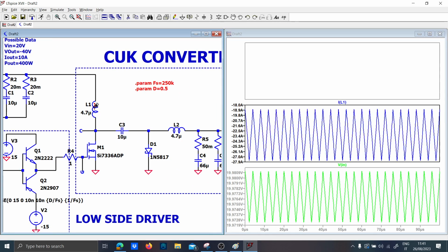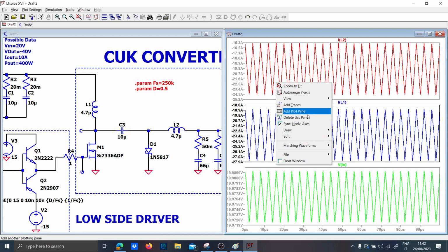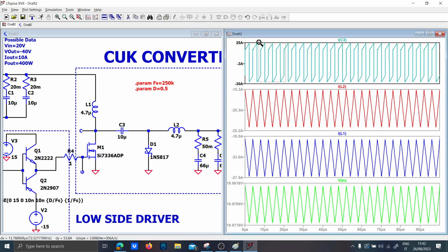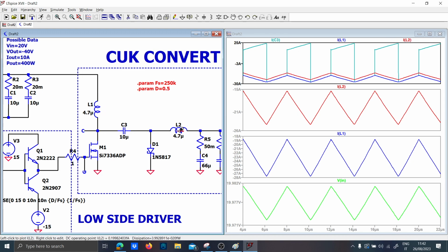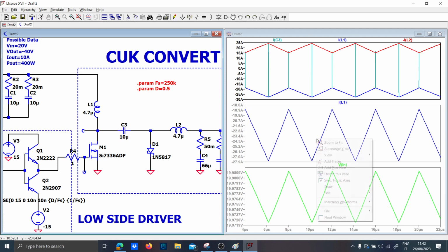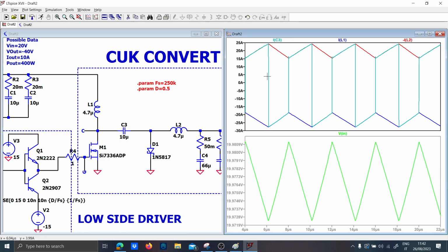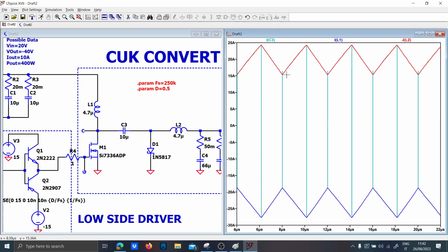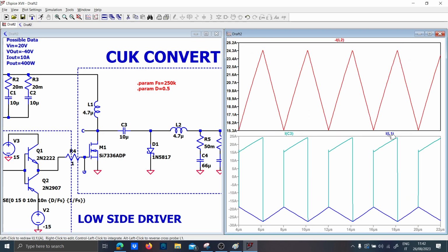Now we see the inductor current in both the inductors. So there is also the triangular shape, as we always know. But let's see the current of this. It is very peculiar because in the first period... okay, so now you can see what I was talking about. Let's focus on this because it is the most important. So you see that IC3 has this strange waveform. It has basically the same waveform as the inductor, but in two different times.